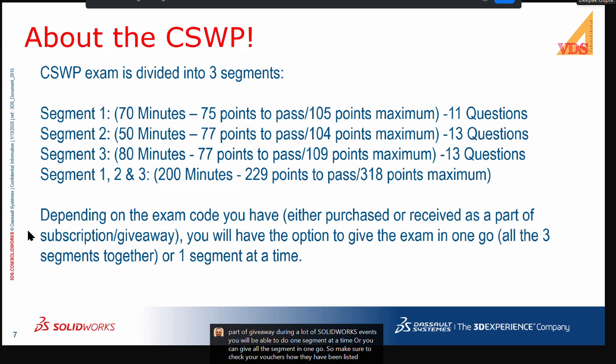So you will be given some components to create sub assemblies and assemblies, and then you will be asked to do collision or interference detections. You will be asked to create a coordinate system, verify center of mass with respect to that coordinate system, override the mass properties, or do some component replacement, and then again verify the center of mass.